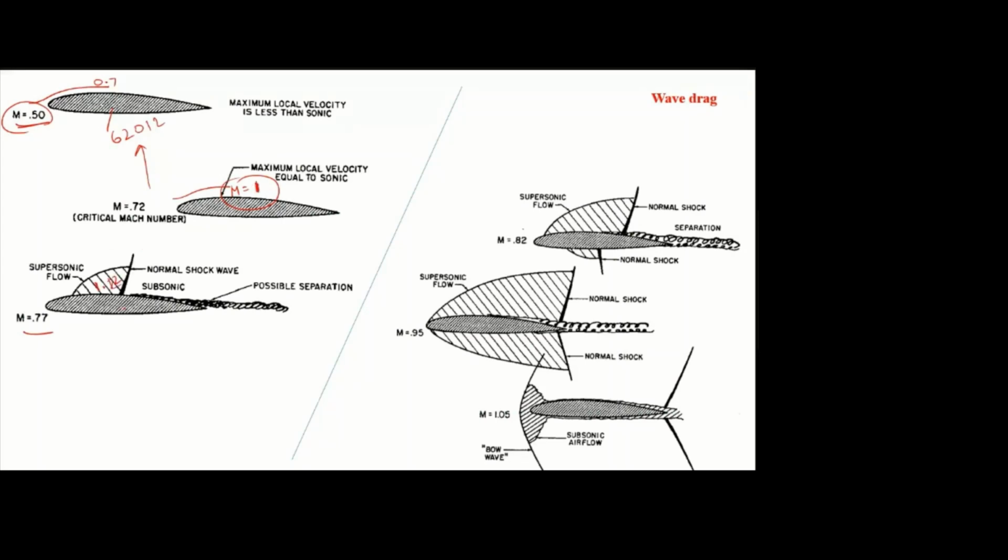Okay, that is the supersonic region. So this is the supersonic region. Here we have low pressure, but here we have high pressure because of the sonic flow. So to adapt to this pressure difference, nature creates the normal shock wave. The nature of the normal shock wave is converting low pressure to high pressure. It's a compression wave. So here we have the high pressure now, and here we have the atmospheric pressure. Due to this pressure difference, we are getting additional drag. That is called wave drag. So the additional pressure drag caused by the shock wave is the wave drag.